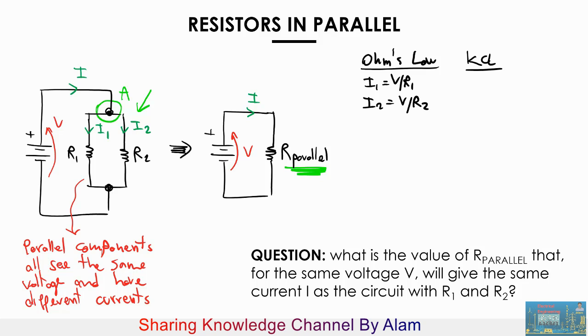And now we're just going to write, and it's actually very straightforward: I minus I1 minus I2 equal to 0. So I'm summing all the currents entering the node and subtracting the ones leaving the node, everything equal to 0. And this simply tells me that I is equal to I1 plus I2, which is kind of obvious if you think of the water equivalent. The water, or the current I, is coming into the node. There are two currents coming out of it, so the sum of these two currents has to be the same, unless some electron got lost along the way.